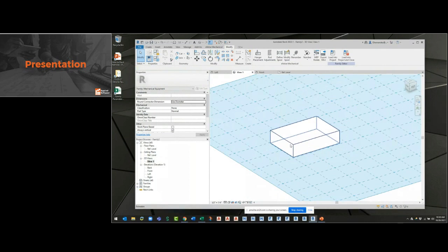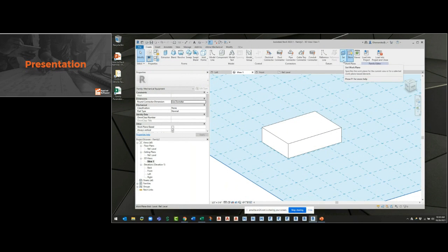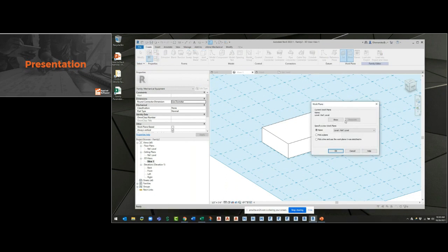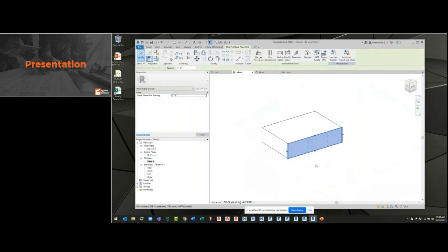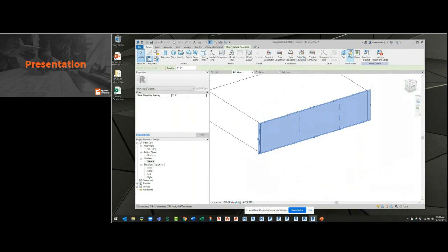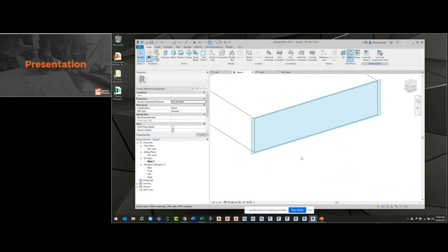Now, if I need to start building off of this, or putting other geometry on here, this is where on the Create tab, the work plane panel comes in. I'll set the actual work plane myself. Now, instead of picking one by name, I can do this visually as well by using this option to pick a plane. So I'm going to say pick a plane here, and I'm going to pick the side of the unit. And notice how with this turned on, I can turn this on and off if it gets in the way. It's the show button here. But now that shows me which side I'm actually going to be drawing off of.